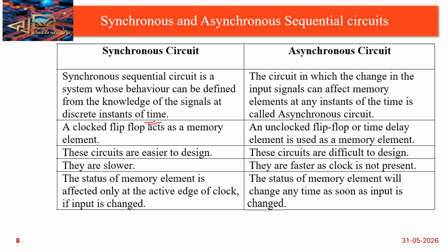Here, clocked flip flops act as the memory elements. In asynchronous circuits, unclocked flip flops are used, and time delay elements are used as the memory elements. We have seen that, right? This is the combinational circuit and this is the memory element. This memory element acts like a delay element.